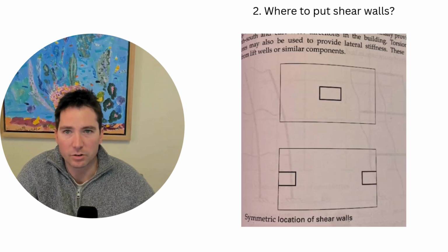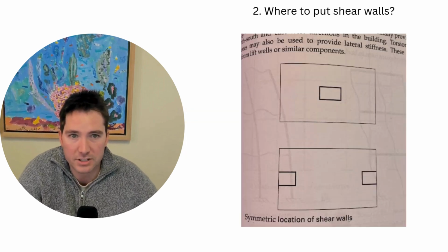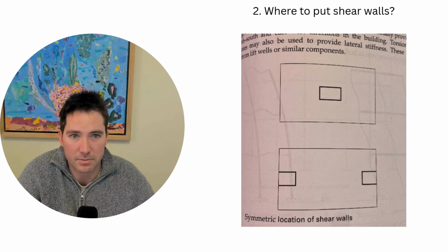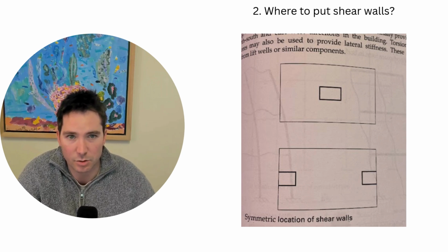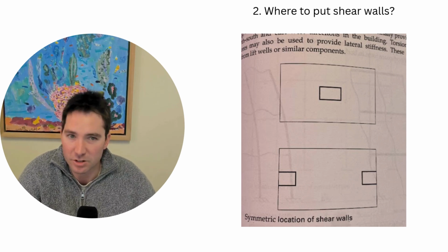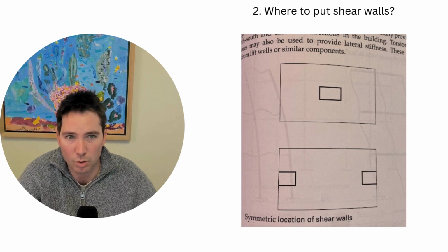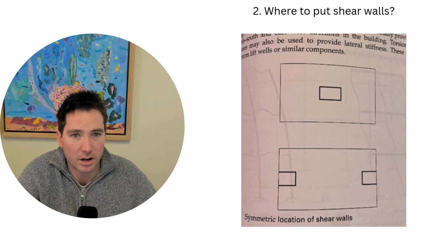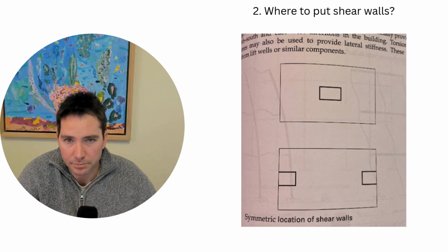So firstly, we're going to look at where to put them if you're designing. Now, the most sensible place to place these shear walls is around, typically on high-rise buildings, the egress stairs for emergency, like fire stairs, and the lift. So there are some voids in your floor plates, and they are the perfect place and the most common place that you will find shear walls. When the shear walls are combined into a box, people often term it a core, so they often get used as core walls as well.